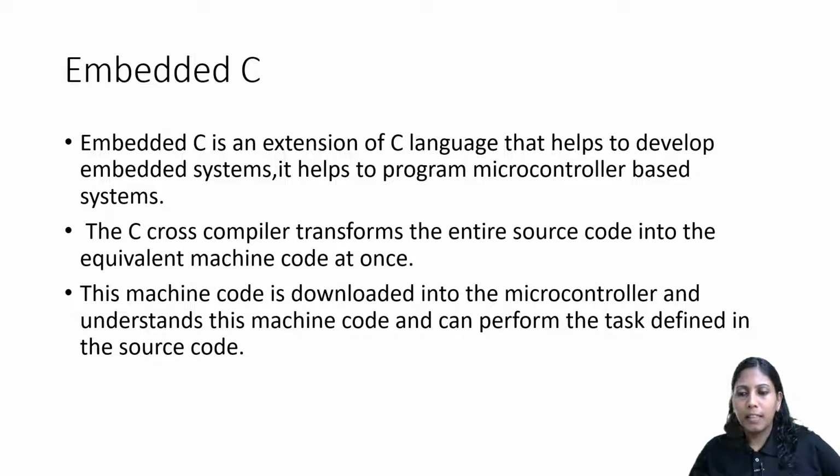And I think that is the basics of embedded C and how we are going to perform embedded C programming. Many of you may have a doubt, which you will have if I am creating a product, say a washing machine: how can I write the program inside the washing machine? We are not going to write the program by connecting the washing machine. We write the program on the host machine, but we test with all the peripherals like sensors and motors. Many relays will be used for switching, because motors work with 230 volts, so we will have a relay circuit.